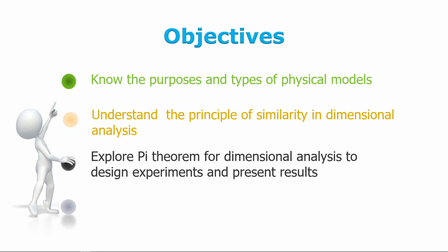So you create a physical model for it, and it's an actual physical model. It's not a numerical model in a computer, but an actual model with a different dimension, whether larger or smaller or whatever. And you need to maintain certain similarity between your prototype, your original system, and your model. That's mainly geometric similarity,